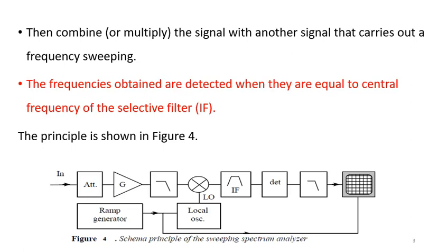There is a maximum amplitude at which your spectrum analyzer can safely operate, so sometimes you need to use attenuators when the amplitude of the signal is too high, much above the safe limit, and sometimes if it is very low, we use an amplifier to boost it.